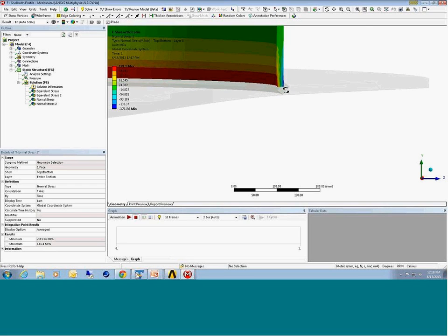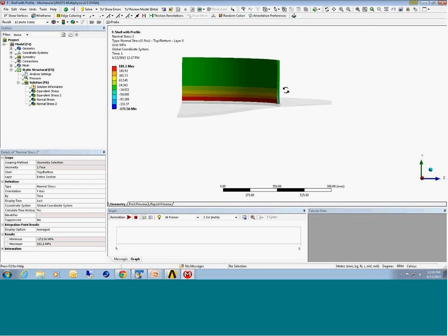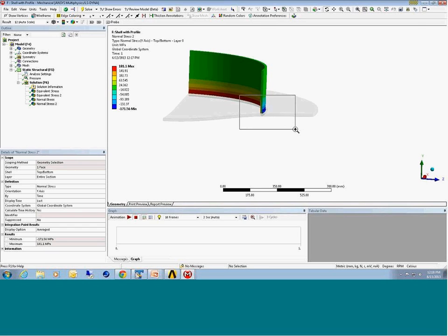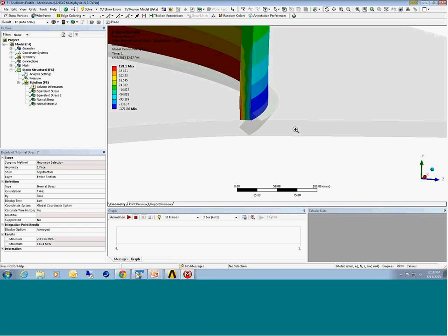And take this stress, and what I would suggest is everybody comes up with their own methodology, not necessarily for calculating the stress, but I might take this stress and plug it into some existing known simple problems where I have a known predicted failure at the number of cycles, and see if I can calibrate my analytical modeling technique with test data.